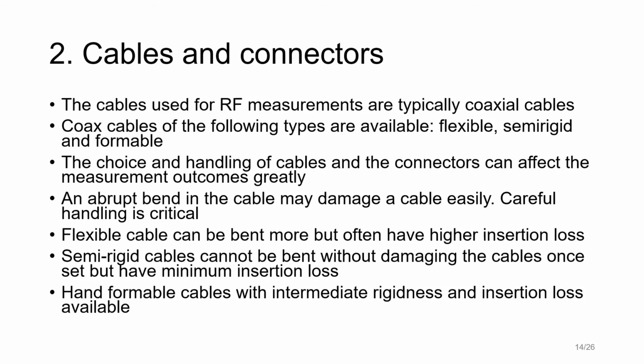Also, exposing the cable to water can alter the electrical properties of the cable. When the cables are exposed to heat, what will happen? The dielectric, which may be made out of plastics like polyethylene, may begin to soften and yield way for movement of the core, which may affect the properties. So these type of damages must be avoided not only for the flexible cables but for cables of all types.